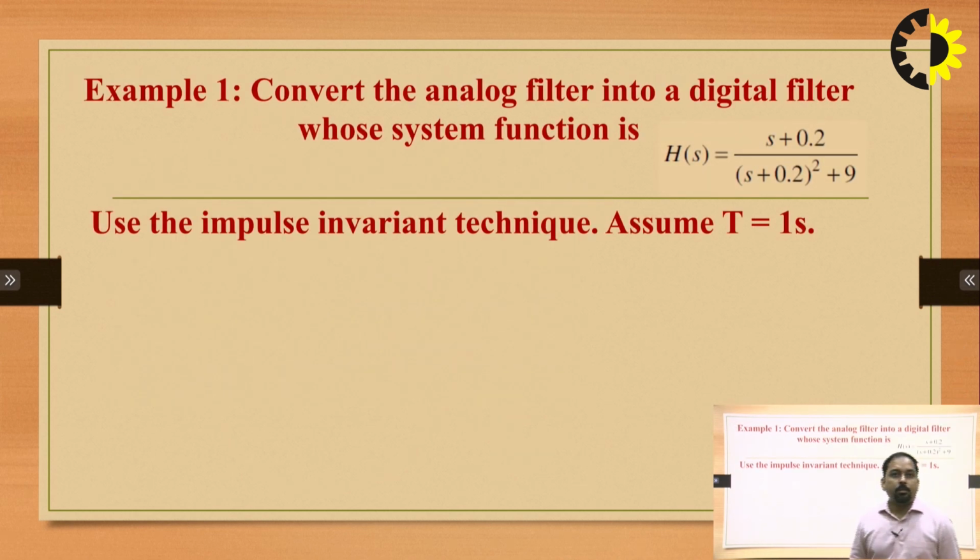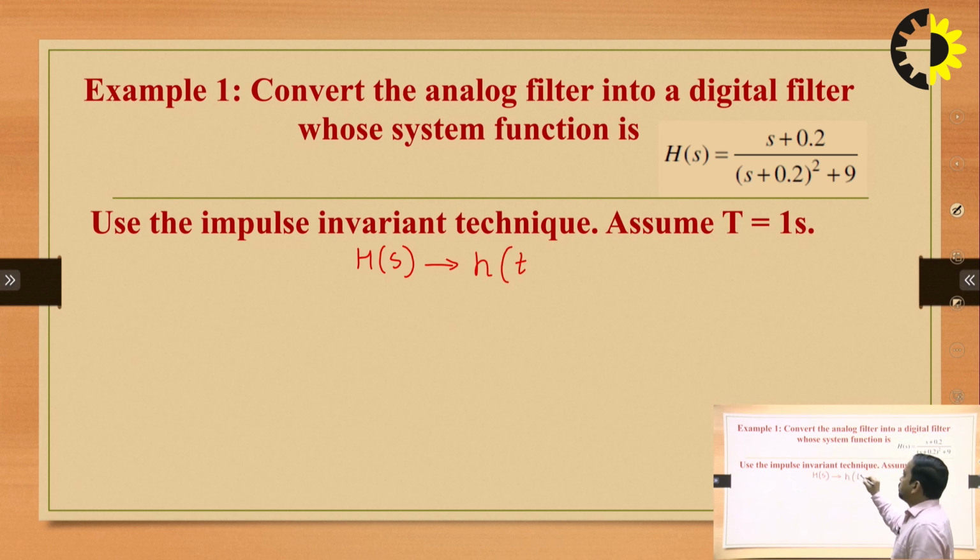Now, based on this, we have certain numericals over here that are associated with an infinite impulse response filter, whose transfer function H(s) is given. The basic theme regarding this is how can we design H(z)? So the basic steps: we'll be having H(s). First of all, I'll be calculating the impulse response of the analog filter, which is h(t).